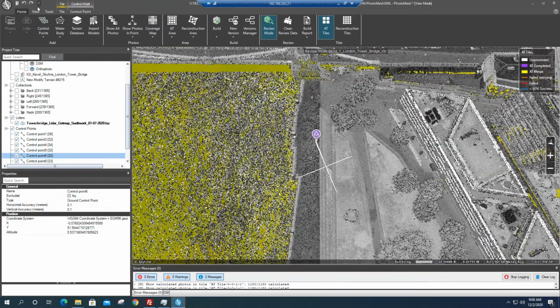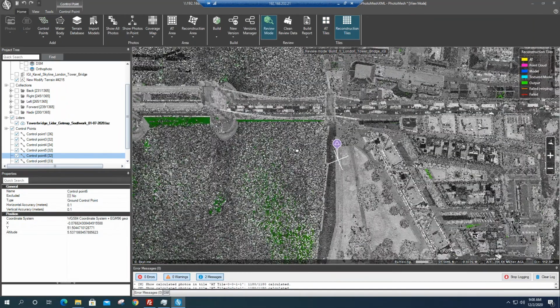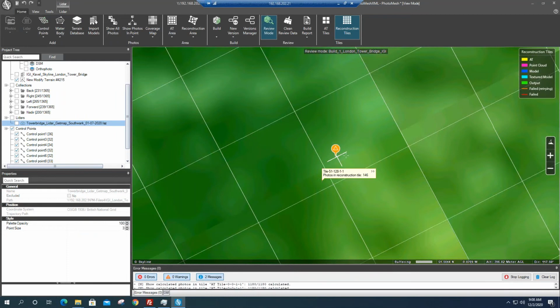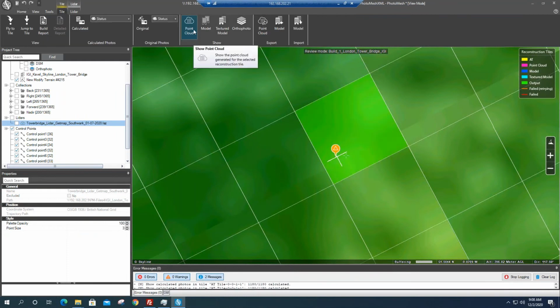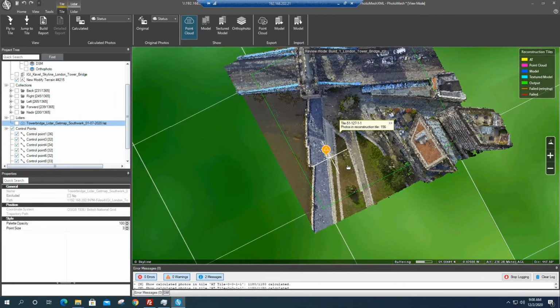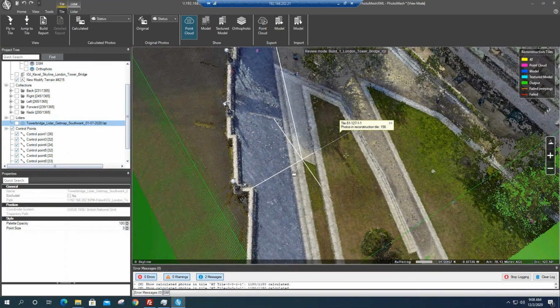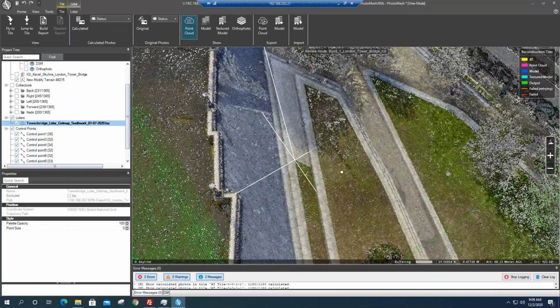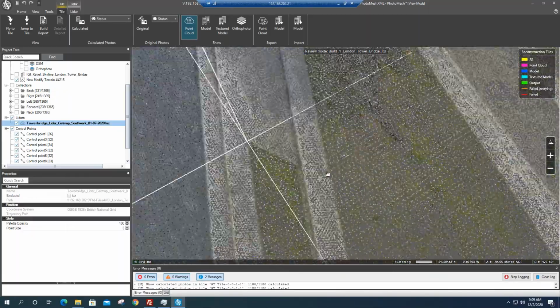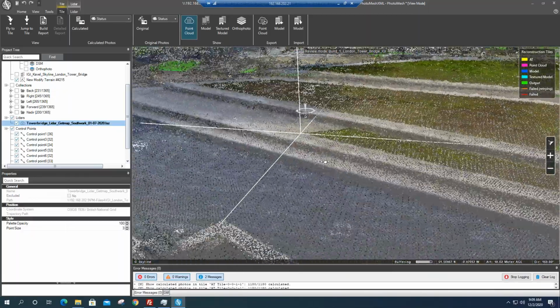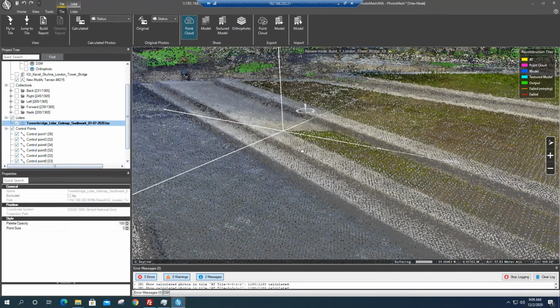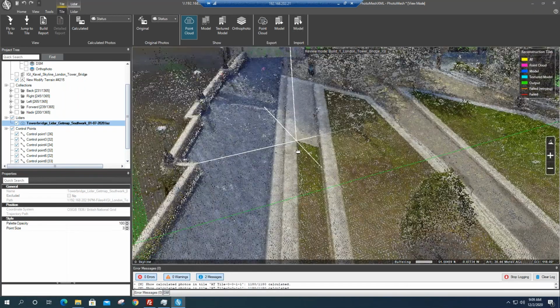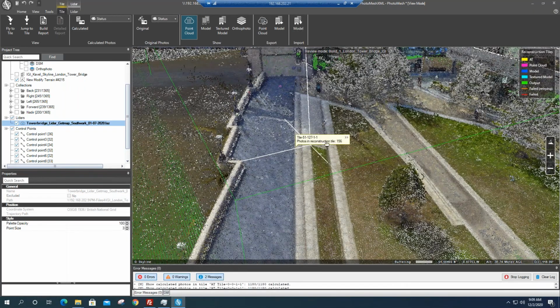So one of the things that we'll look at as part of the processing is, when we process the full 3D data, this is the image-based point cloud. So this is the point cloud that was produced from the integration of all the oblique images. And you can see the LiDAR data, and they align very well together. So it's able to really create a sort of where the LiDAR fills in.